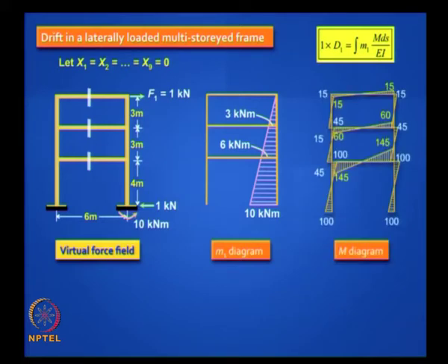So this was the original bending moment diagram. This is approximate. So the error in your answer is due to the error in this, not due to the error in small m1 diagram, but we live with that error. You know the actual deflection will be more than the value that you calculate, because the beams are not infinite, they are flexible, so they will add rotations theta, remember the earlier class. So it will be more, but this is a lower bound solution that you get.